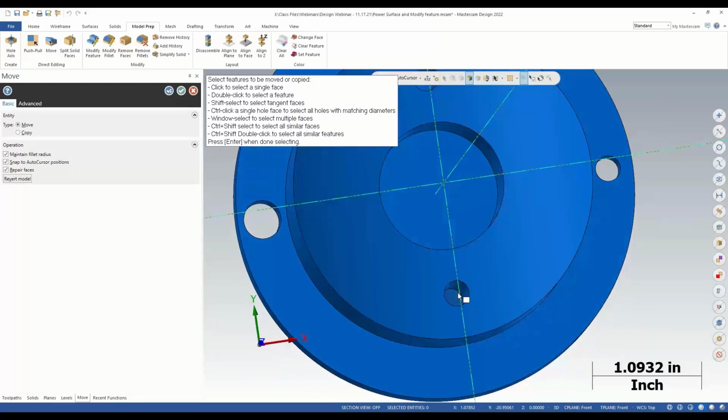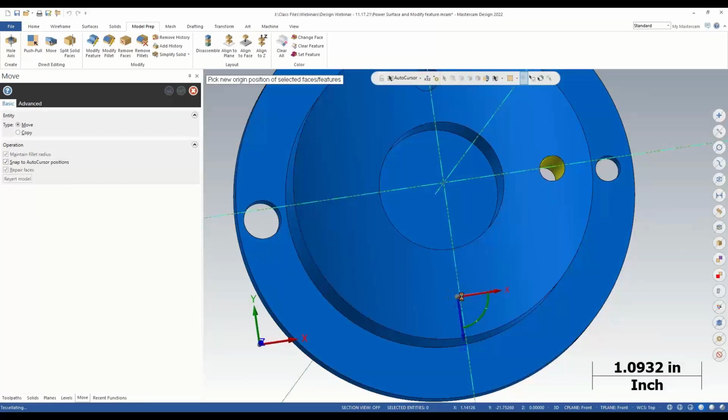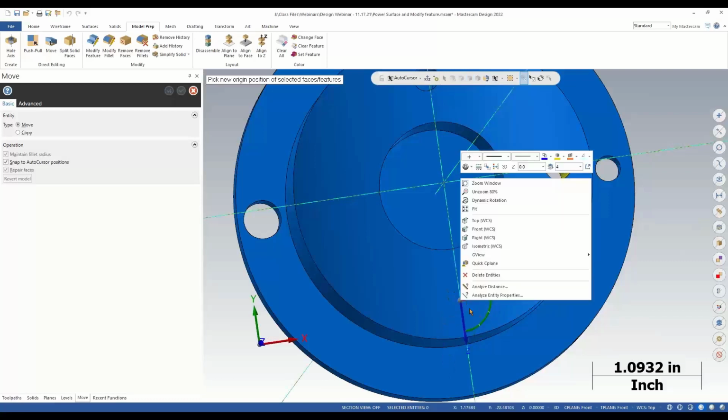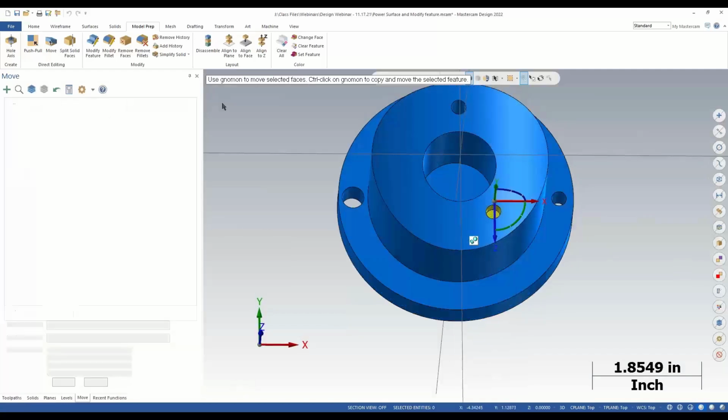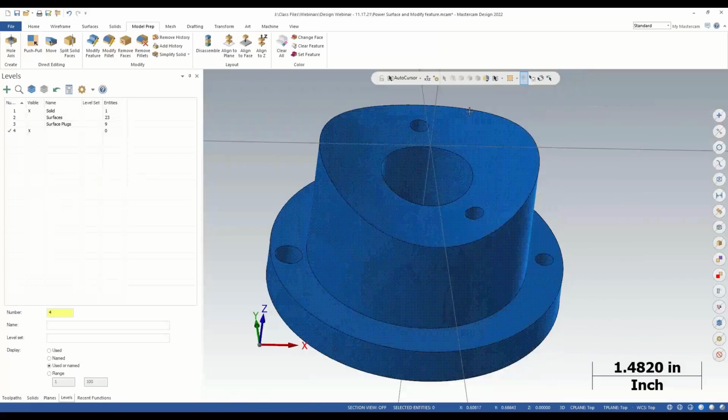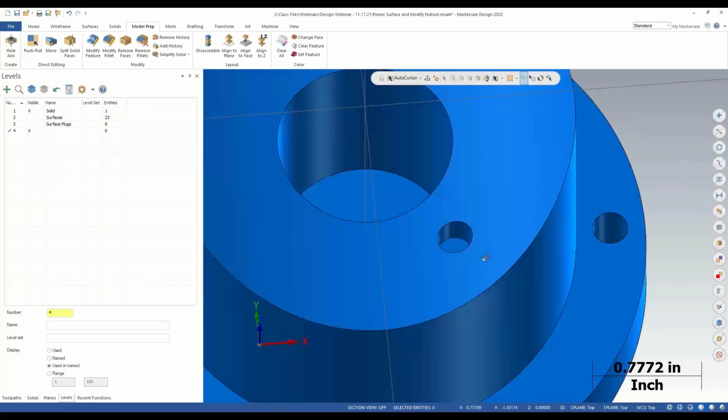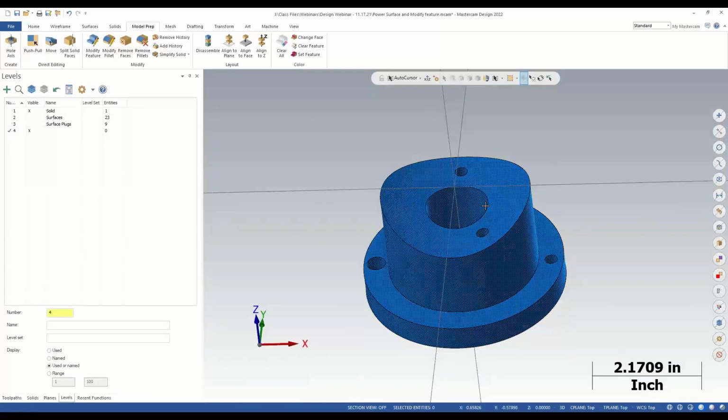So if I wanted to move this hole right here, let me go to the top plane. There we go. I can move this hole wherever I want, granted that it can actually still extrude through the body. So I can move the hole right here, green check, and there's my hole. So push-pull will let you modify a feature based off the normal of that feature, while move will let you actually physically move that feature wherever you need it.